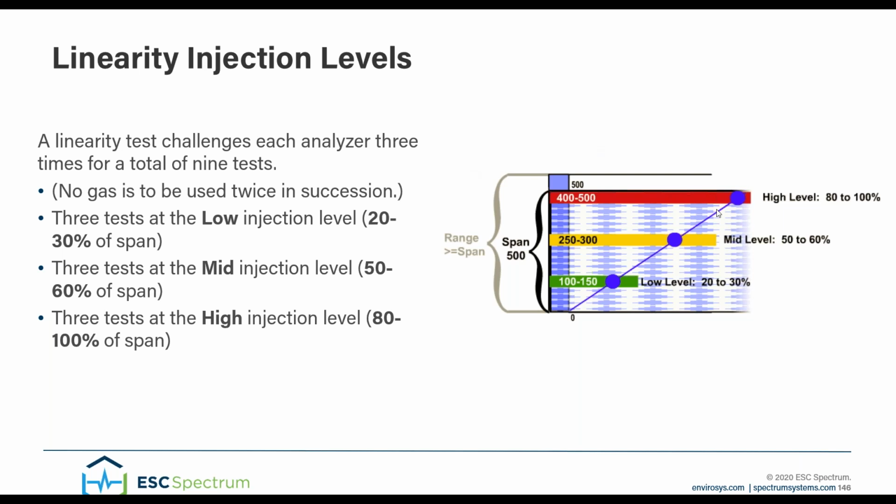All right, the question about the maximum potential concentration: can that be set to whatever you want? No, you cannot set the maximum potential concentration to whatever you want. So to speak, you can't go willy-nilly with those and just throw whatever numbers you want in there. There are certain requirements that you would find in the Code of Federal Regulations, depending upon what the analyzer is or the parameter that you're monitoring, so which analyzer is being used, what controls are being associated with that. Are you using O2 as a diluent?